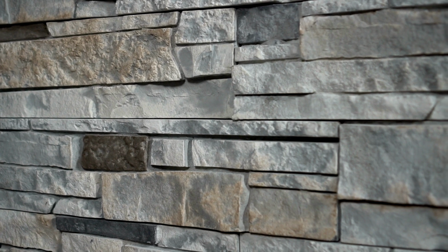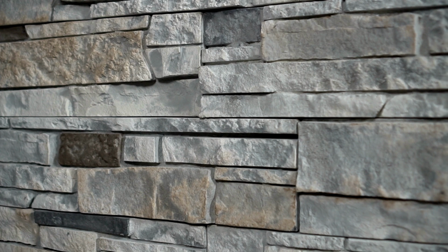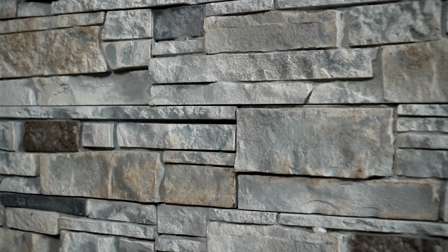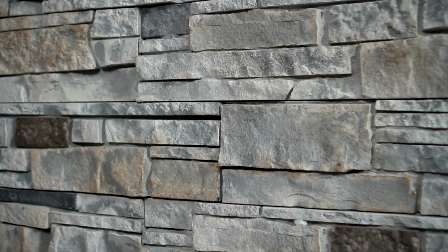When completing courses, cutting factory edges is unavoidable. However, avoiding cut edges in high visibility areas and near focal points is not difficult. Care should be taken to plan accordingly. All cut edges should be close to and directed toward an inside corner.